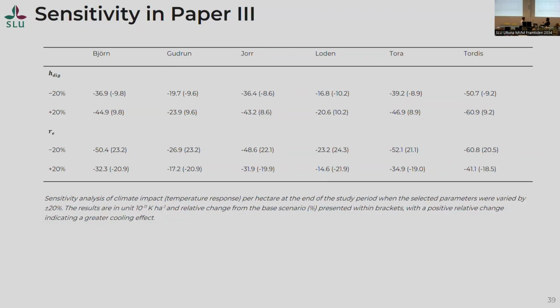But this digestate effect, I mean, the digestate contains a lot of carbon because in the biomethane conversion, a lot of it does not get converted to biomethane. But how it stays in the soil is a bit more uncertain. What we can expect is that because it has already undergone one kind of biological degradation, the biomass which is there is more resistant, and most of the carbon which ends up in the digestate is from lignin, which is more resistant to degradation. So probably that will have a longer retention time, it will degrade more slowly and it will stay in the soil for longer. Yeah.